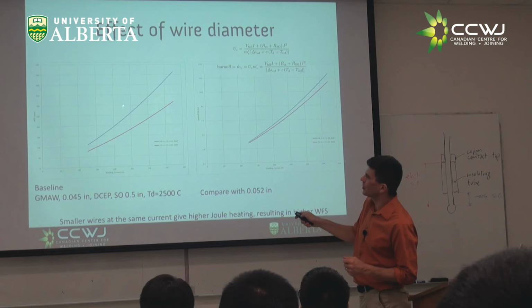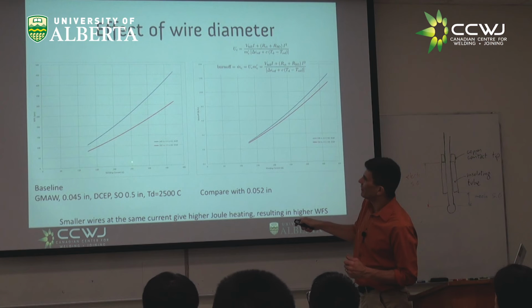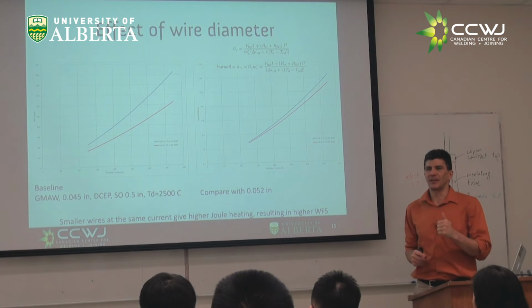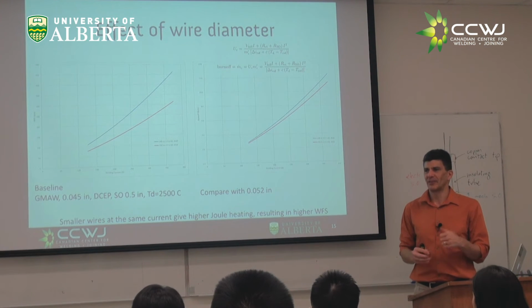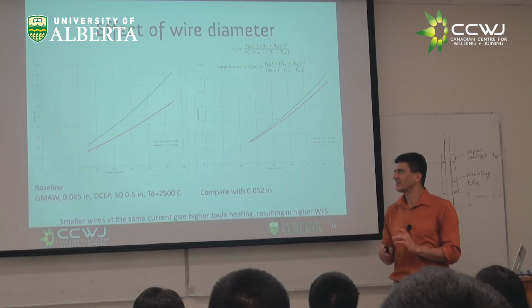You see this curve, the blue curve? 200 amps, 200 inches per minute. You have 250 amps, more or less 250 inches per minute. So it's kind of convenient because with that 045 wire, I more or less know where we are standing. The other wires, I have no idea. But this one, I do.